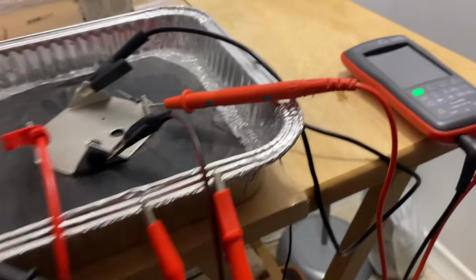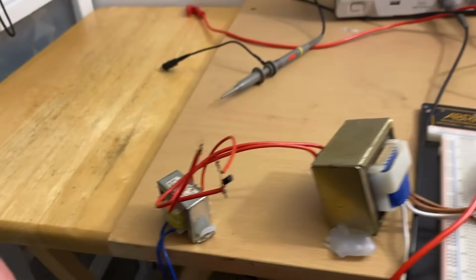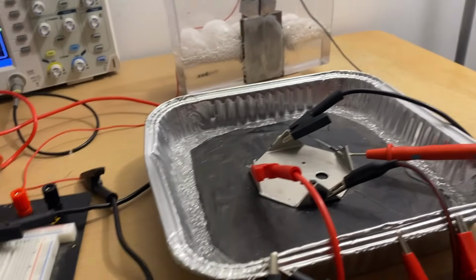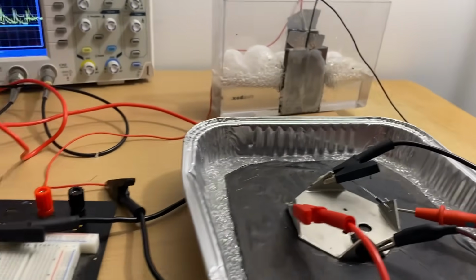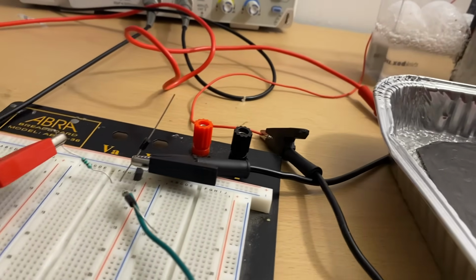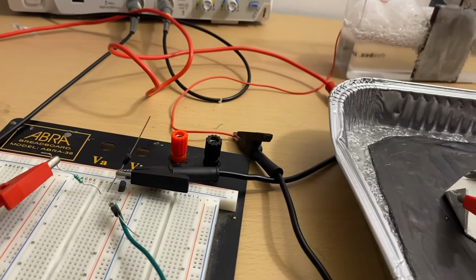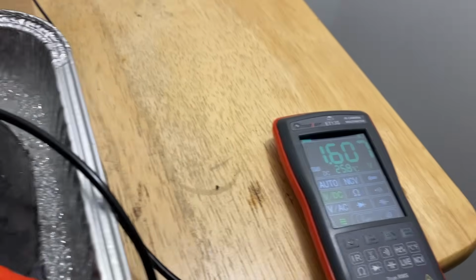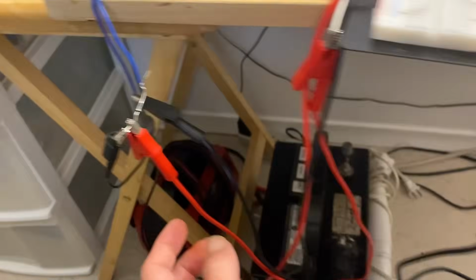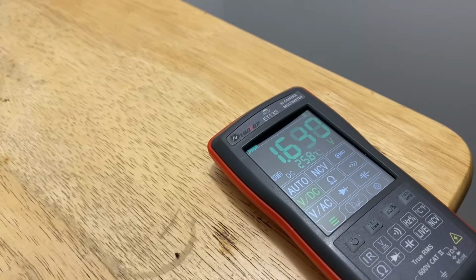So what happens is the extra here from the cell is getting reverse modulated by the transistor, and that's how it reinforces. We can kill that reinforcement, and I'm going to show you that. I'm going to turn the motor off here. I'm going to show you the voltage. So the motor's off, so it's going to climb a little here. And what happens is I've got the feedback here. So I'm going to find the feedback wire and disconnect it.